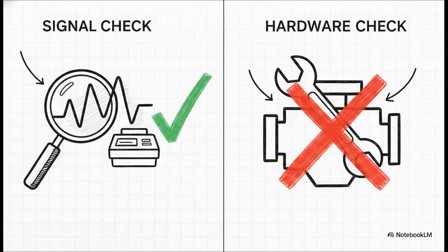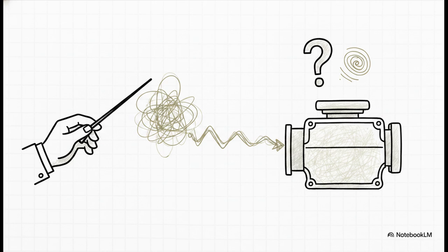Remember our quiz at the beginning of the explainer? If you have 0 fault codes on the engine, but you're seeing a load-sharing imbalance across the bus, you almost certainly have a governor-level signal issue. A miscalibrated or drifting milliamp signal perfectly mimics a mechanical engine issue. I really want to hammer this home because this exact scenario wastes hundreds of diagnostic hours. A subtle load-sharing problem looks exactly like an engine issue.